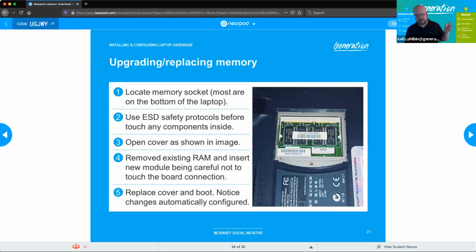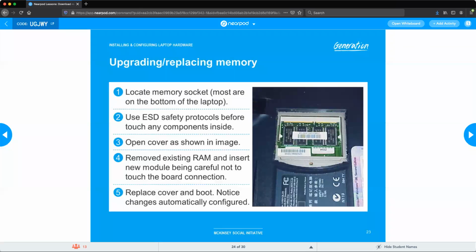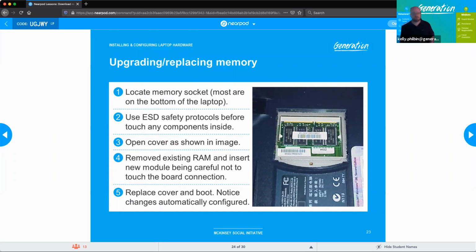And then on mobile devices, like phones and stuff like that, some of those screws are magnetic, some are not. So that comes into play too. But definitely organize your work. And then if you've never worked on that particular type of computer or laptop before, as you're getting into it and taking the cover off, what's the first thing you should start doing? Taking pictures. Beautiful. Taking pictures so you know where everything goes.